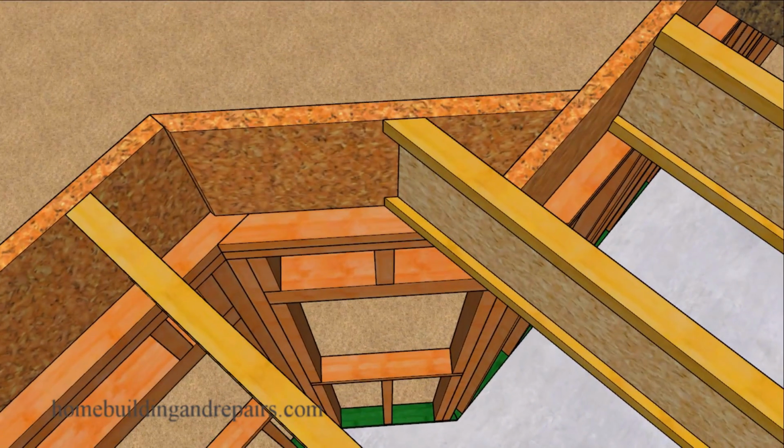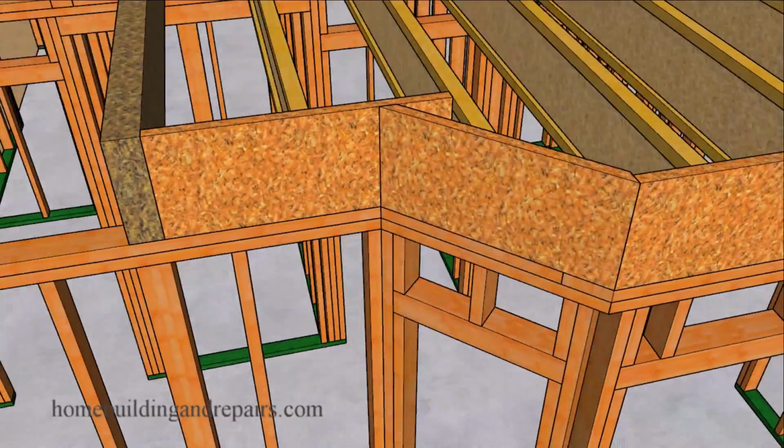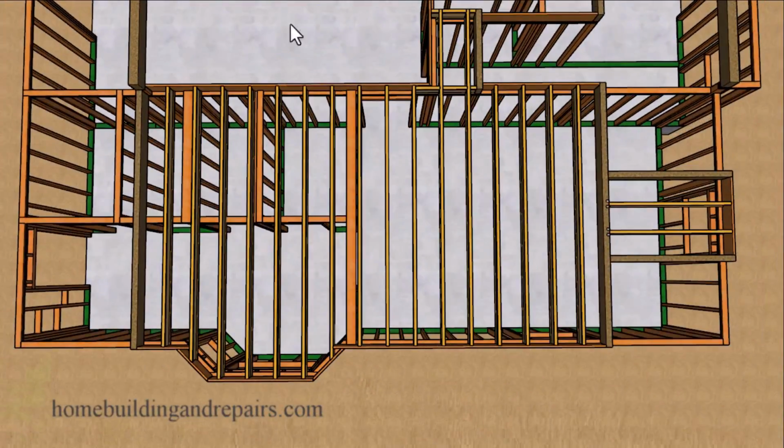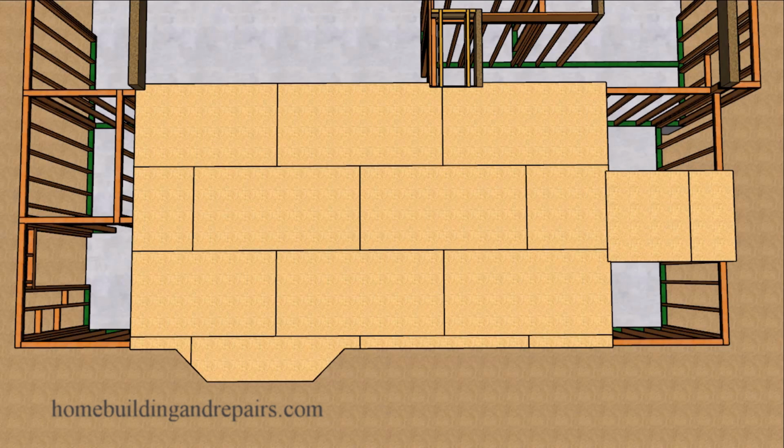Now we have another bay window, 45-degree angle on the joist here. Let's go ahead and take a look at it from the outside. So we have our rim joist. Again, the beam is full bearing, post under it to provide us with a nice load transfer. 16-inch on center joist spacing that you're going to need to put some thought into if necessary. Keep in mind that some of these joists will need to be repositioned for a variety of different reasons: plumbing, heating, and in some cases even electrical.